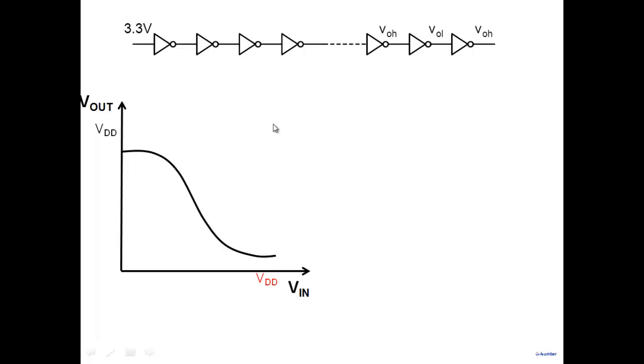Well, one way of doing that is a similar plot that we have been doing. You take this as V out and take this as V in, same characteristics, you replot it. And the stable values that you see here are points like this here. This will define your VOH and VOL. Okay, so in a long chain, the system would stabilize at these points here.